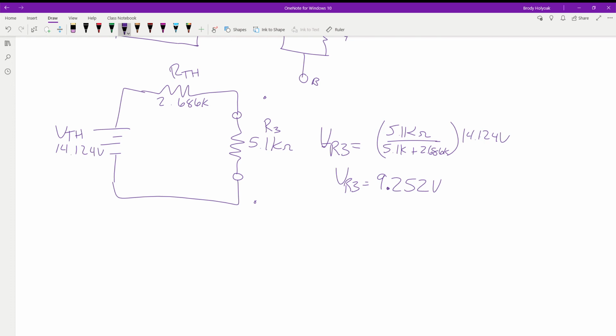Just look at it and take a second and analyze it. What should this answer be about based on the ratios? And that's the cool thing with the resistors, is that these ratios will always hold true. So if you have more resistance on one side than the other, you're going to have more voltage across there. And then across the whole circuit, the more resistance you have, the less current you have. So is that actually VR3? That is VR3. This is 100% VR3.